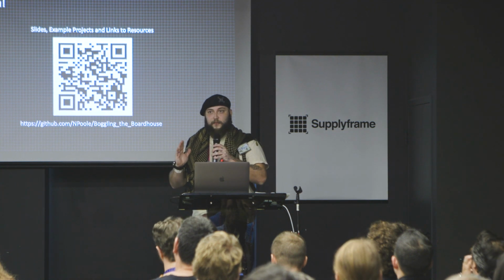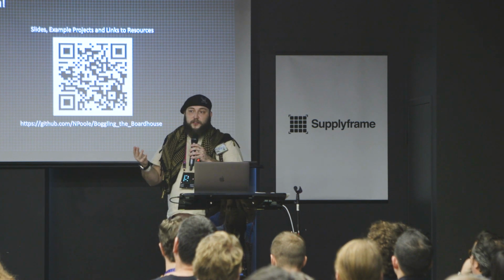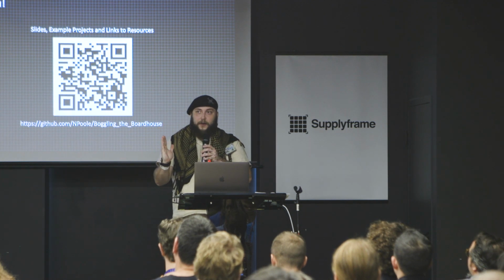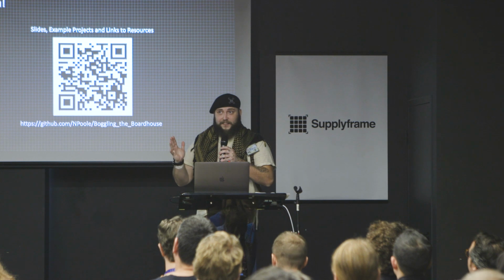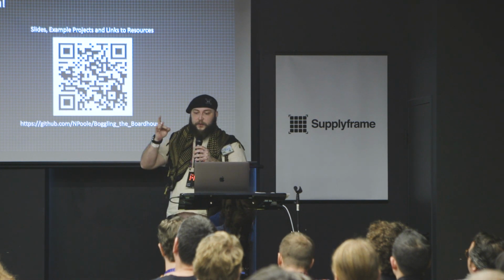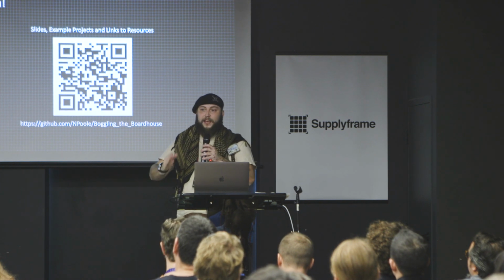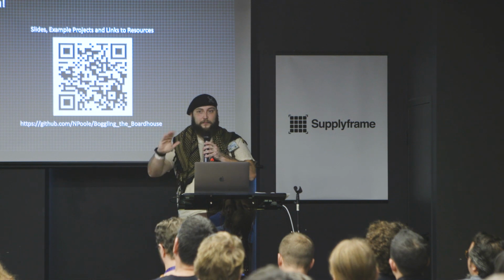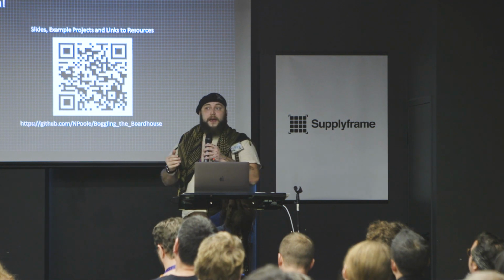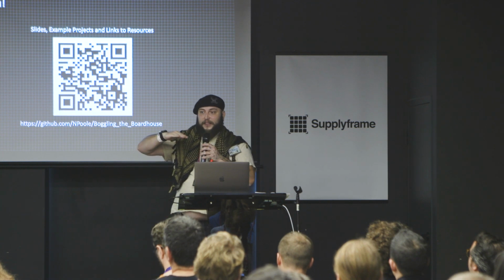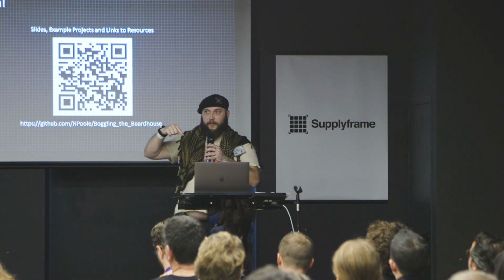A lot of board houses will have a thing where you can get edge plating, and you just specify where along the edge of the board you want the copper to go. And it costs a lot more. But if you just put a really big diameter plated through hole and then tell them to mill most of it away, you end up with a little concavity that's plated over the edge. So that's one way you can do it. You have that on the top layer, and then on the bottom layer you have a landing pad for it, and you just put solder in there.